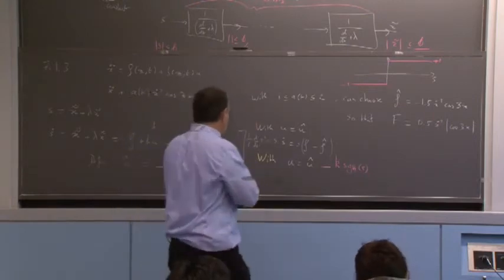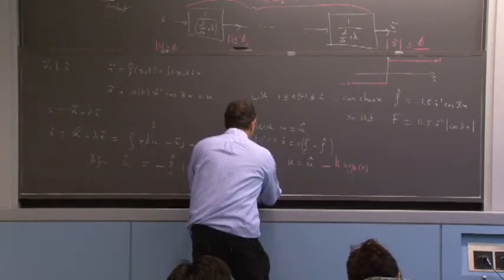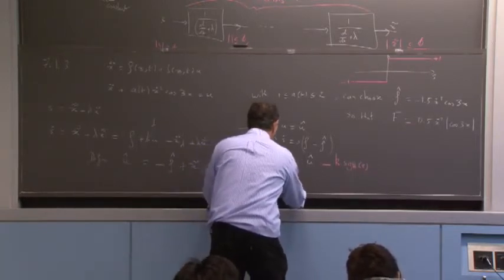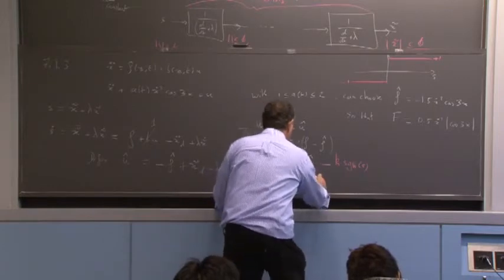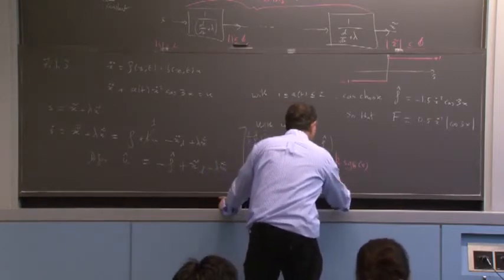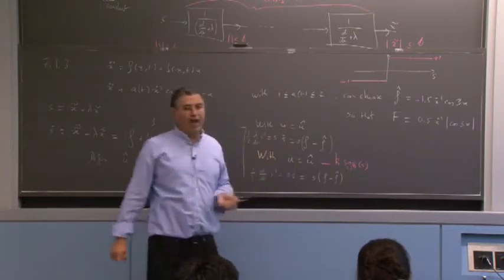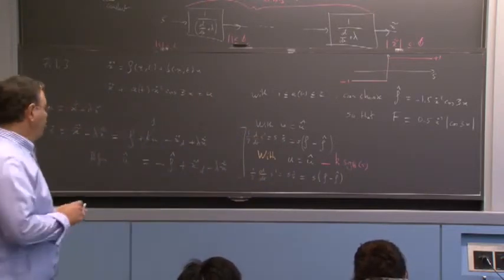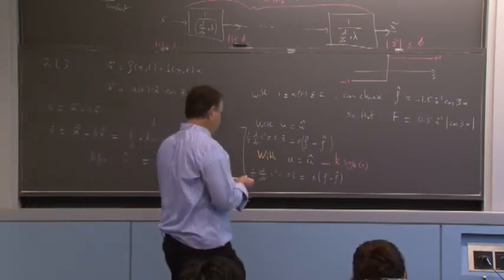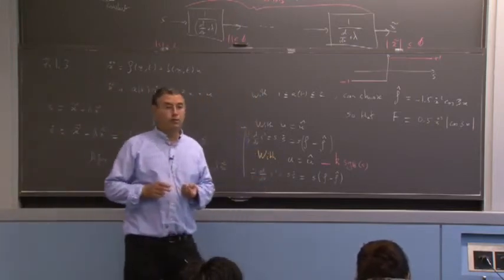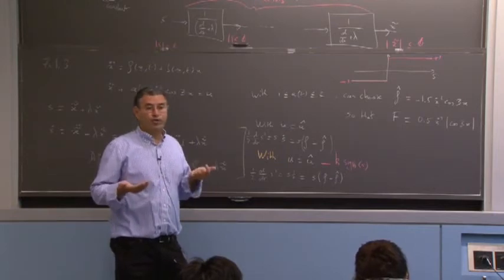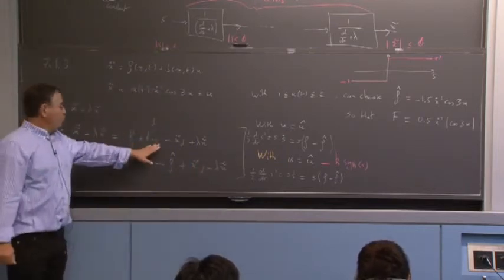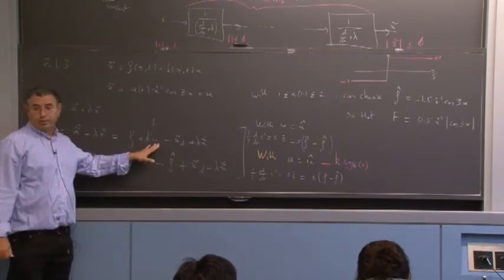Suppose we do this. What can we say about 1/2 of d over dt of s squared? Well, it's still equal to s times s dot. It's still equal to this term, F minus F hat. But then we have the extra term we've just added to u, so we've added a term to s dot.